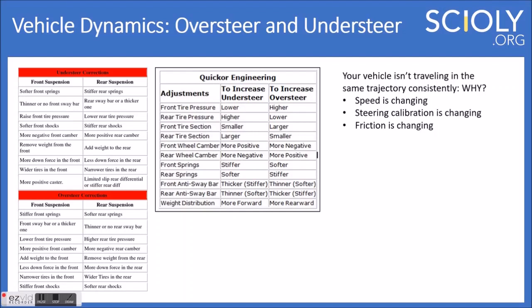So something I found with using nickel metal hydride batteries in 2017, when we had the curve with EV, was that if I recorded a time that was lower than the previous run, so say the car went faster, it would typically tend to understeer, so it would have a larger radius, a larger arc that it would travel in. And then it would displace the vehicle to the right of the target.